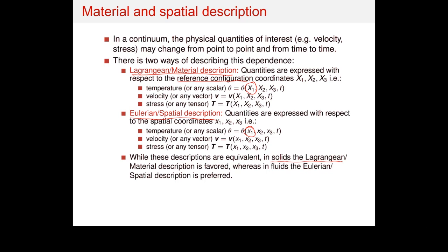But when you have large deformations, such as in fluids, the original configuration and the current configuration can be completely different. They would look very different. So using the original configuration to describe the displacement, you would not get anywhere. This is why in large deformation, you would use the Eulerian description, and the Eulerian description is all about the current configuration. All right.